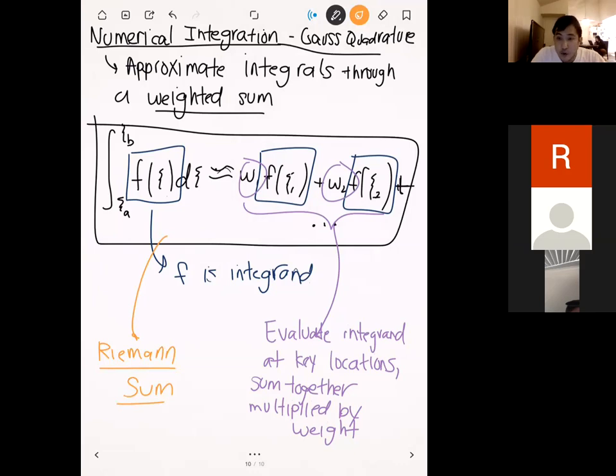All right, so the question is: do more curvature and critical geometric features mean more weighted points? That's a great question, actually. The number of weighted points that are chosen depends a lot more on the order of the function that you're putting in. If you have a quadratic function versus a cubic function versus a linear function, that's the bigger driving factor for how many points you should include for your weighted sum. Yep. All right, any questions on this?